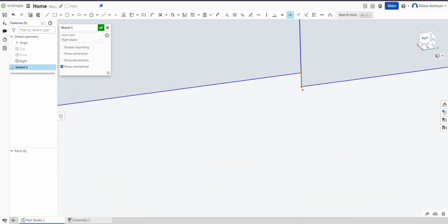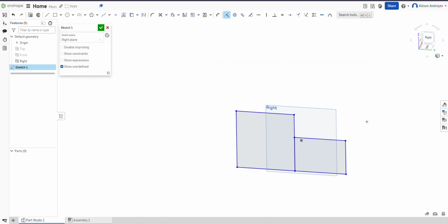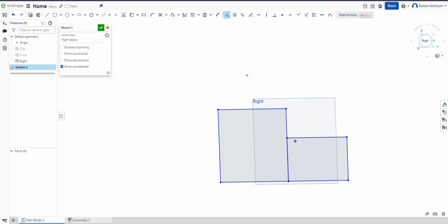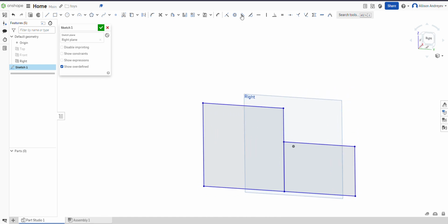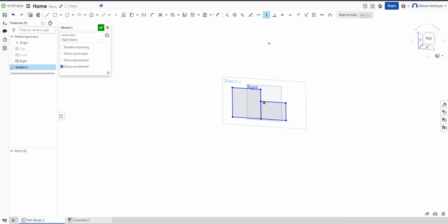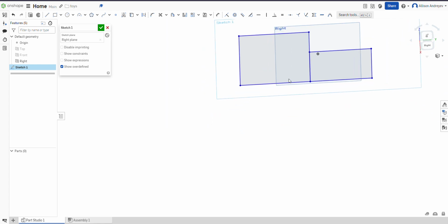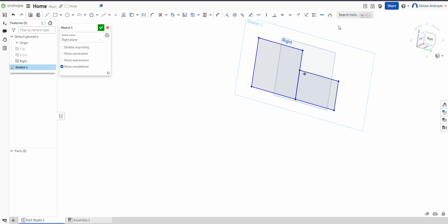I'm going to create a coincident between, not midpoint, coincident between these 2 points, to make sure that they're aligned perfectly. And these are my 2, but you can really make any heights. It doesn't really matter unless you're gonna print it, then it does matter. But I'm gonna make sure that these lines are horizontal using these, and that these lines are vertical. Okay, it seems like they are, so I'm gonna keep it at that. That's gonna be my house now.